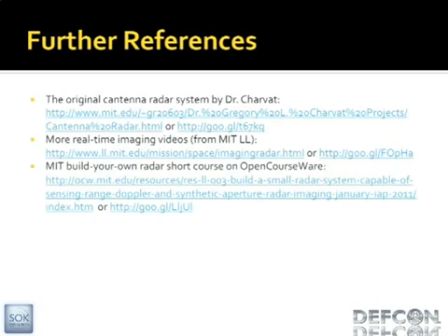And the other thing is there's actually a way of disambiguating those. I didn't talk about this, but you can chirp up and you can chirp back down. If you think about it, the effects are a little bit different, because the Doppler shift is always going to change the frequency in one direction. But if you chirp the other direction, it'll shift it backwards. So all you have to do is figure out what's happening there and you can disambiguate them.